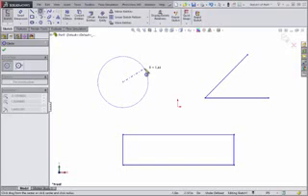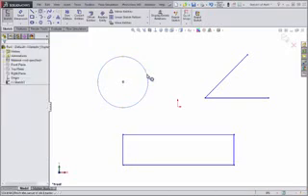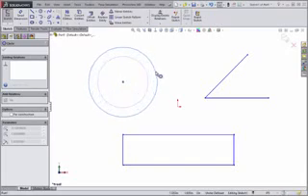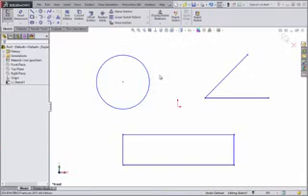Now it's important to note that these numbers are simply used to approximate the size of the geometry you're creating. As you can see, the entity can still be resized by dragging one of its points, so you only need to get close to the desired size when initially sketching geometry. To precisely define and lock the entity size, you need to use dimensions.